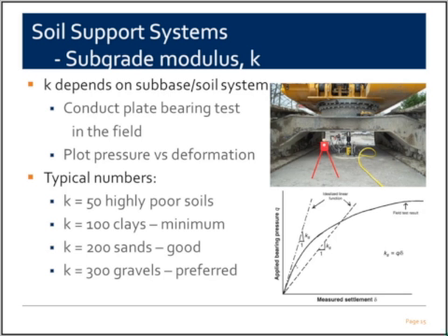And as you see here, you need to bring the hydraulic ram, you have to find a reaction. In this case, they brought a grader. They're loading it, and you need to measure the deflections, and how are you affecting the soil properties with that grader right next to it? Those are all issues. But anyway, there's a 12-inch plate bearing test. It's very expensive to do. The 12-inch bearing test does the same thing. It requires less loads, but still not very often done because of the expense and the effort involved in it.